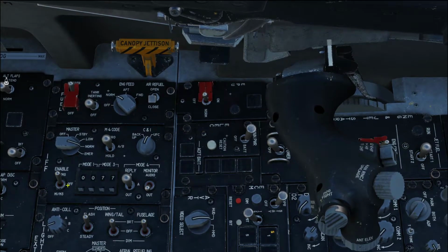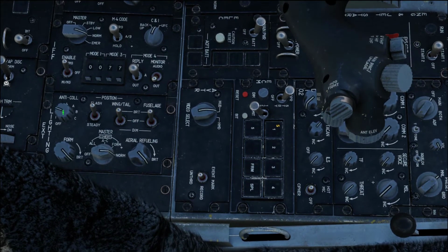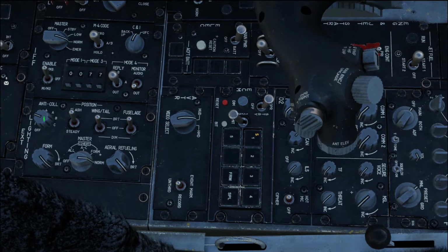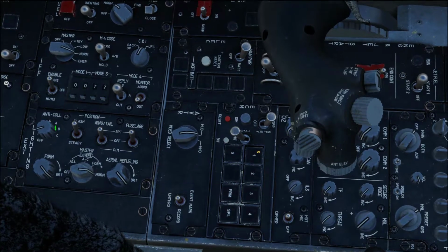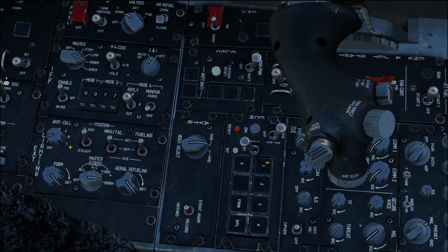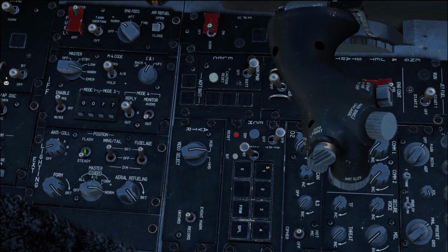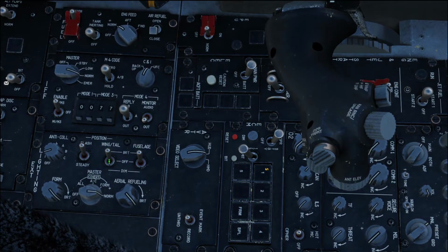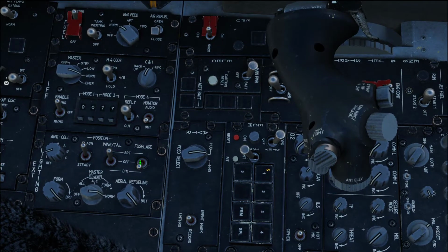The first knob towards the left turns on the anti-collision. 1 means 1 blink per second, 2 means 2 times per second, similarly 3, 4. Alpha, Bravo, Charlie can be programmed as per the flight or the pilot discretion. Next to that is to keep the position lights flashing or steady on. Then we have the brightness control for the fuselage and wingtail lights. The bright position keeps them to maximum brightness, off and similarly to dim.